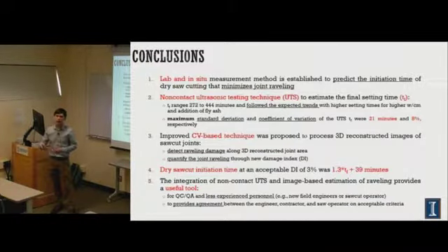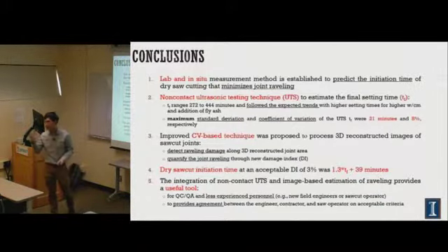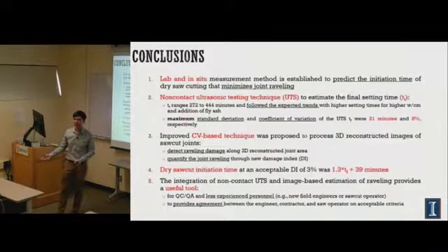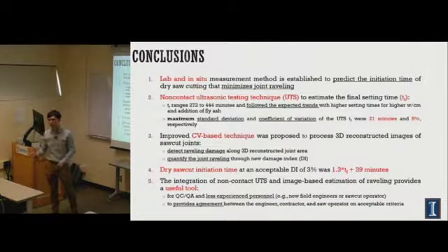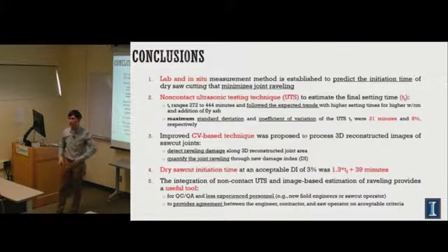In the field, what they used to do to know the setting time is maybe they use some knife or some tool, and they crush on the surface. If it's good enough, then they say, okay, the concrete set, I'm good to go for pouring the curing compound or doing the saw cut, right? But it can vary here and there, because like you say, the temperatures, the wind, the environment factors.